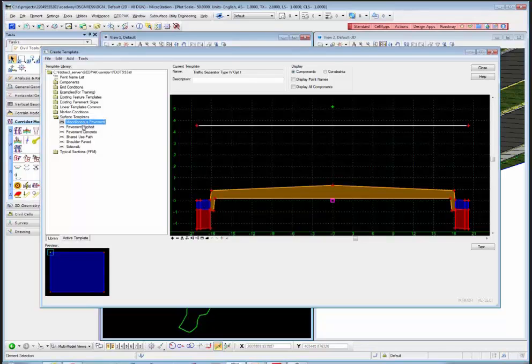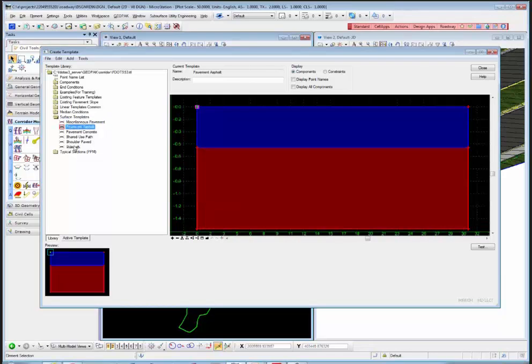Surface templates. Surface templates are kind of like the existing feature templates, where only these are proposed surfaces. So you might have a terrain boundary that represents an intersection, built, and you need to apply what's called a surface template in SS3. You would come over here and pick the pavement asphalt, and now what you're doing is giving that... what's the word I'm looking for? It's an intersection boundary that's not a square or something standard, and you need to apply depth to it. So an irregular shape boundary is what I'm trying to say.